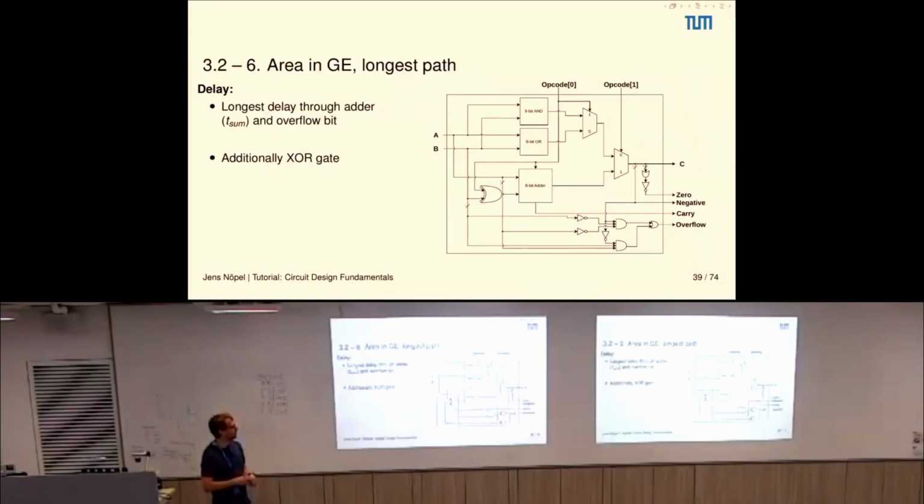So you don't use the actual numbers for the specific vendor you have used. What you use instead is the gate equivalence. What you do there is you pick one gate of that vendor. Usually that's the NAND gate of that vendor. And this is your baseline. Divide all the numbers by the numbers for that NAND gate, and then you end up with the gate equivalence.